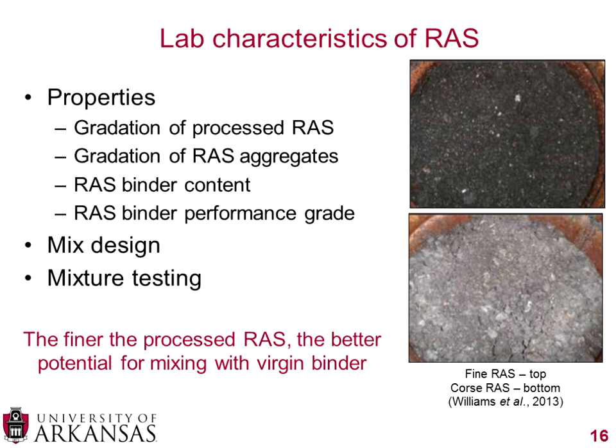Another important lab characteristic of RAS is the mix design. How does the incorporation of RAS influence the mix design? And then finally, the mixture testing. At the end of the day in the laboratory, what sort of property changes are there when you include RAS in your mixes? I've said it a couple times, but it's certainly worth repeating: the finer the processed RAS, the better potential for mixing with the virgin binder.